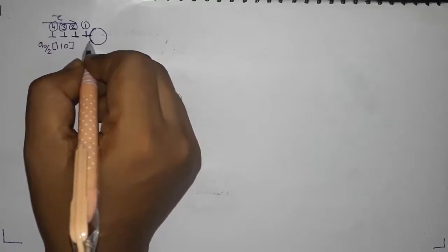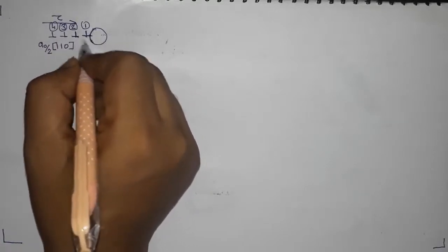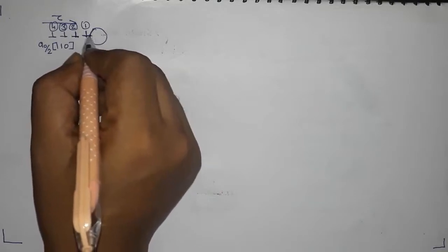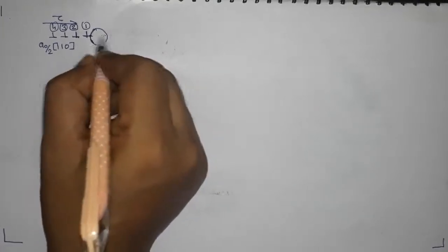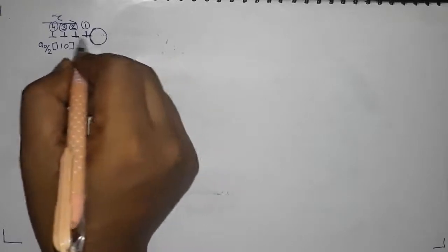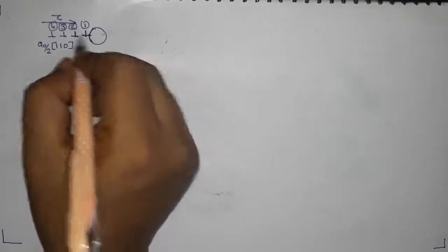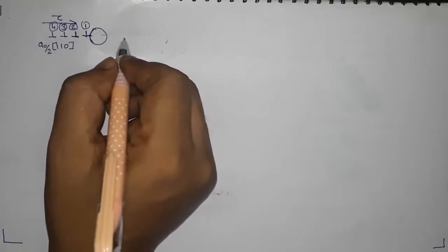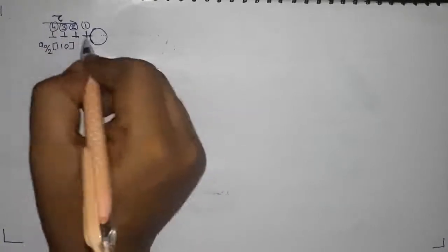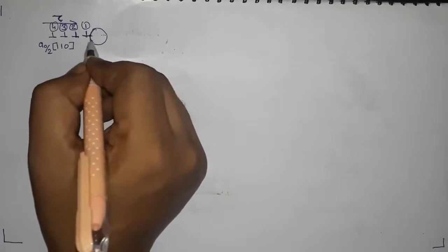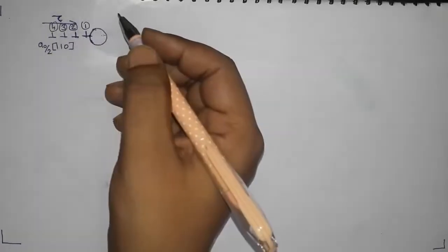Now I will have to do something so that this barrier is either crossed or broken, so that the dislocation can pass through, move on, or do something, so that slipping is allowed. If that does not happen, then there will be no strain, no slipping, so stress will cause no strain.